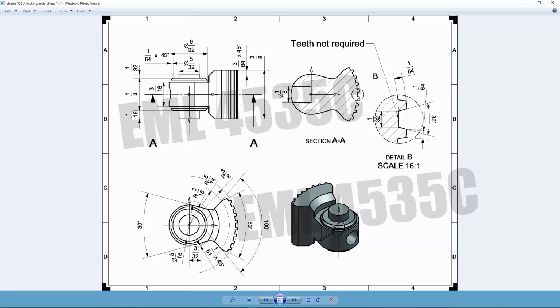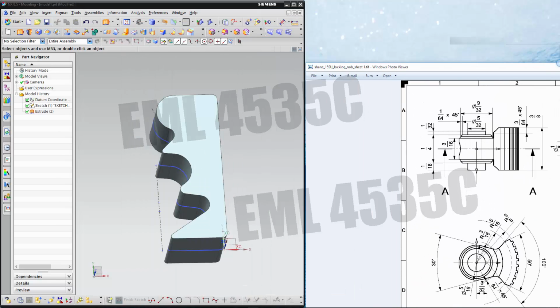Okay, so nothing fancy. It's just the sketch is a little bit hard, and you don't have to do the teeth. We gave the dimensions, and I'll show you a little bit in the video, but you don't have to. Okay. So a couple ways to do it. You can extrude this shape, the section AA, then cut from the top and the bottom a little bit into this, then make another 2 cylinders and drill the hole. So that's what I'm going to do.